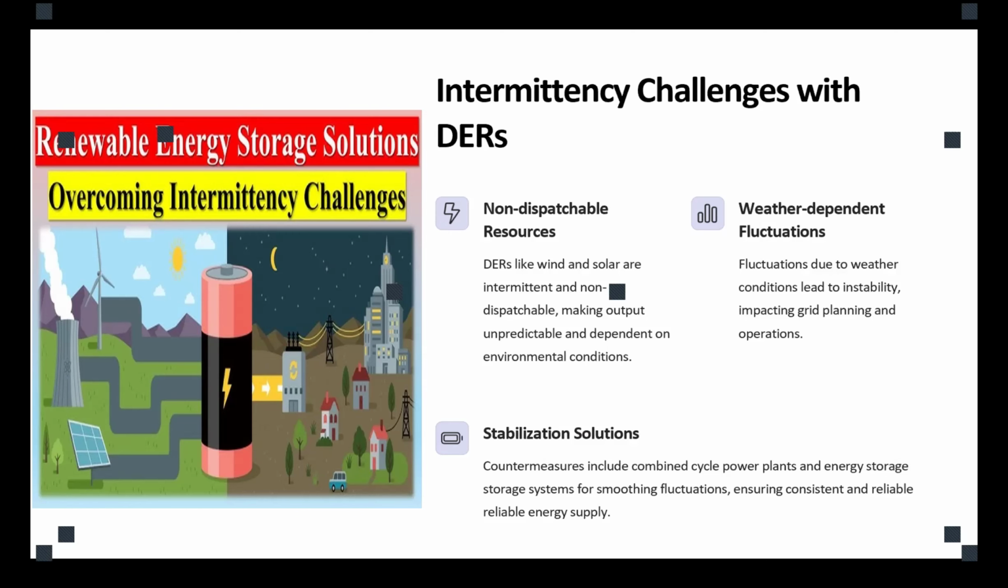And another part is the stabilization solutions. We already talked about how inverters and inverter-based resources affect power flow analysis and transient analysis. We saw how integration of the inverters changed the Jacobian matrix in power flow, adding a huge amount of complexity for analysis and for keeping the system stable.